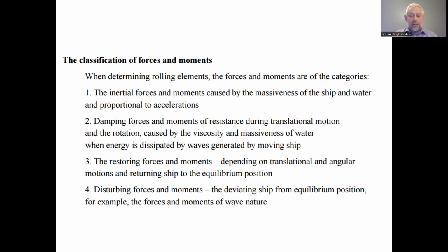And for these forces, as well as for heeling, for vertical rocking, and for the trimming of the ship, for pitching, for these three kinds of rocking of the ship, we have restoring forces and moments. So it is probably more correct to say that these are not forces only, but efforts, because some of the forces are moments. Formally, the operations over forces and moments are the same when finding the elements of the ship rocking or motion under controls. And the fourth category, disturbing forces and moments, deviating the ship from the equilibrium position.